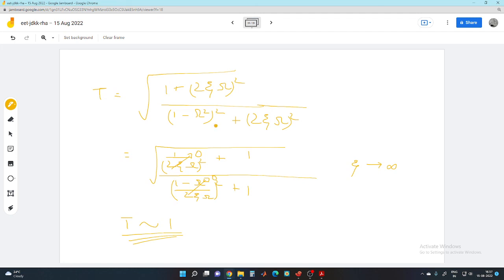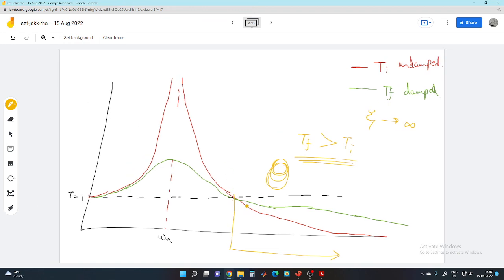It will definitely reduce the effects in the stiffness or resonance dominated regions, but it will actually have a negative impact or a counter impact in the inertia dominated region. So in inertia dominated region, if you want a very low transmissibility ratio, it is advisable to have a very low damping factor. So I think that is sufficient as a discussion.